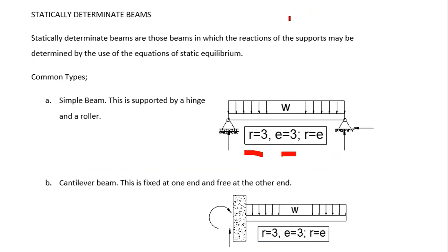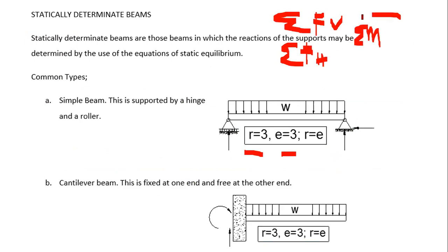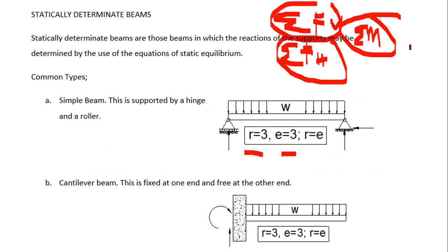Equilibrium equations, I'm referring to. Summation of forces vertical, summation of forces horizontal, and summation of moment. So there are 3 equations available for determinate beams.